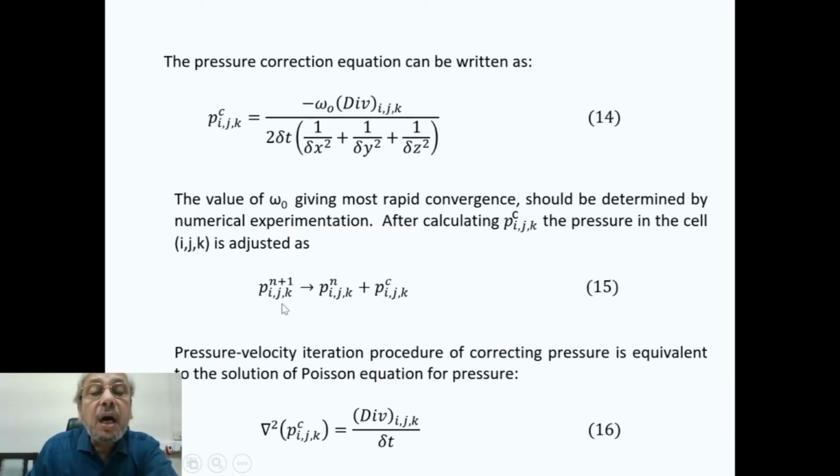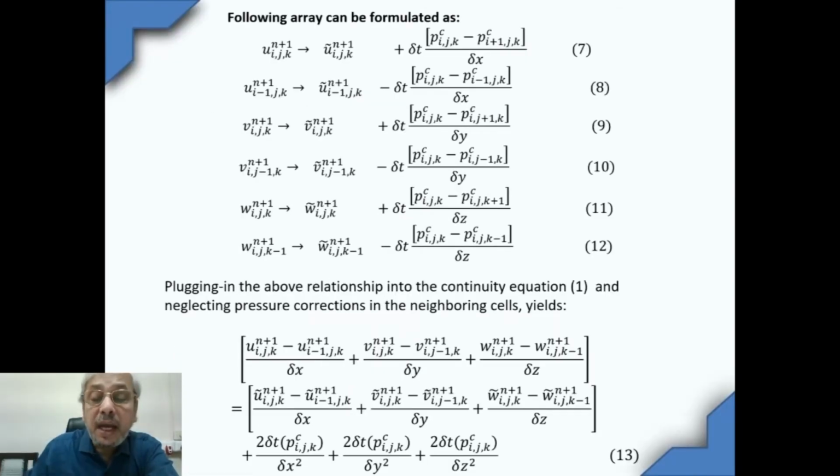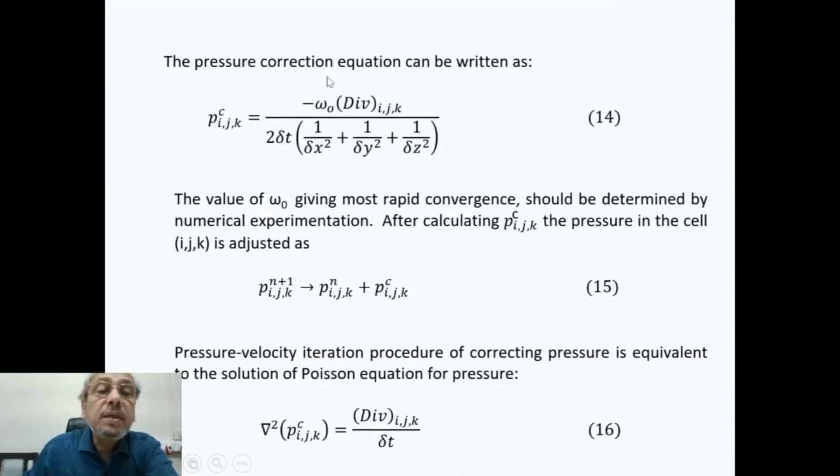But you can jolly well understand that we neglected all the neighboring terms to get this explicit expression. So you cannot expect that this pressure correction is exactly the correct final pressure correction. And that is why here also we have used, instead of an equality sign, a tends-to sign.